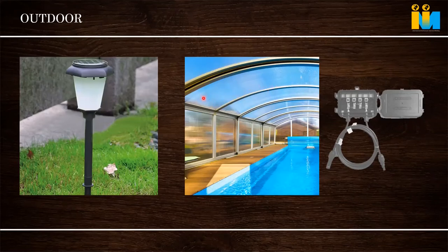In this case, you can see it should be transparent. For roofing, polycarbonate UV sheets are used. It should not become yellow after some time. The color should not fade, or it should not become a milkish color after some time. That is the haze effect. One is the yellowish effect, one is the haze effect. Both should not be there, and it has to withstand higher temperature, maybe 70, 80 degrees. Sometimes spot temperatures can come also. Like solar junction box connectors, which go for outdoor application for a longer time, like we have spoken, 25 years of service they're asking. So Noryl is used, which has good weatherability properties.